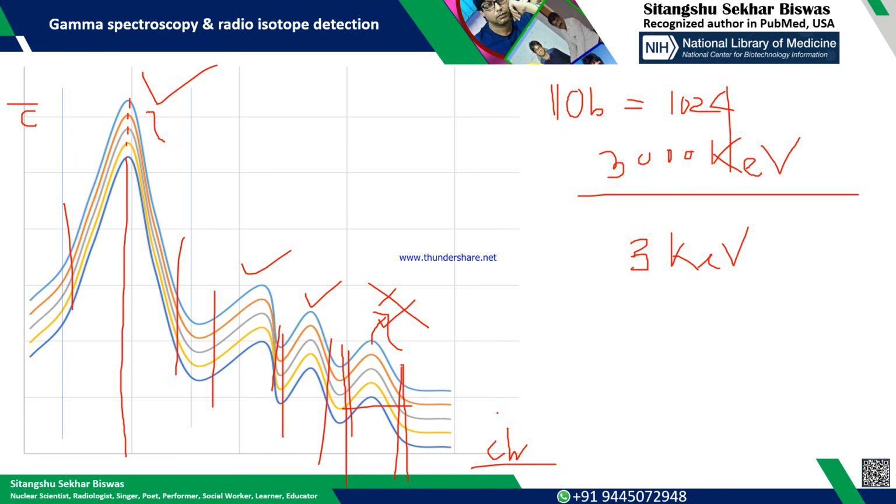Once the gamma photon is incident on the nuclear detector, the sensing element, whether fission chamber or crystal, gets excited, and there is an orbital change, meaning an electron will jump from one orbit to another, which will cause some electron flow through the external circuit if a potential difference is created.